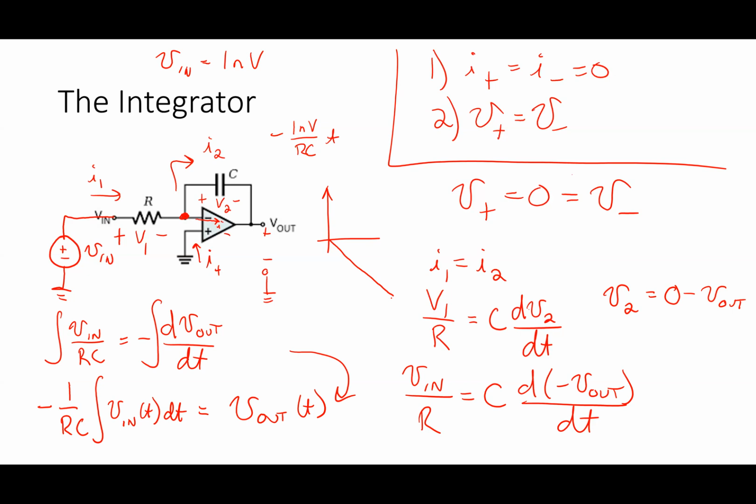Okay. So in terms of building a circuit like this, it's got its problems. But there are ways of dealing with that type of problem. I can do things like occasionally discharge that capacitor. How would I occasionally discharge the capacitor? Put a switch on it that shorts it every so often, or something like that. It's a common problem. Sometimes we say we need to reset these circuits. And again, it's commonly used in controls.